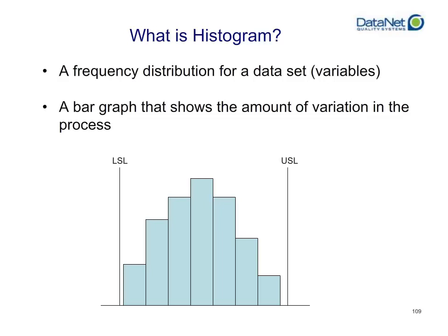It is effectively a control chart on its end for a period of time. So if you were to imagine taking a control chart that you have a sufficient amount of data on and pretend that each subgroup that you've plotted is representative of a pebble or a game piece for a Connect 4 type game, and you tip the control chart from a horizontal view to a vertical view and let all the different subgroups that you've collected fall onto the ground and into a row, and you want to see what the distribution looks like.